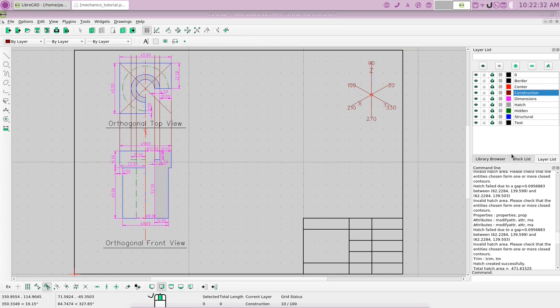Okay, so we'll be drawing our isometric portion using lines at these particular angles. 90 degrees will be in the Z direction, X will be 30 or 210, and Y will be 150 or 330.